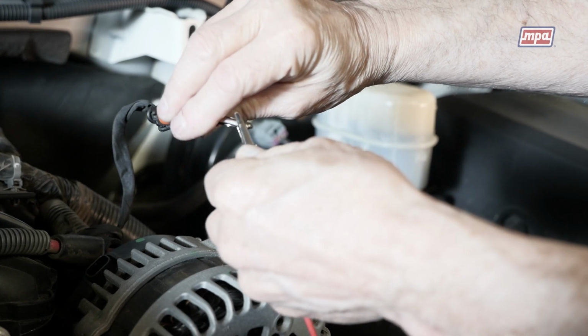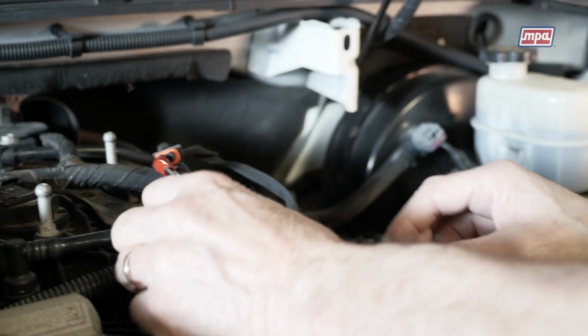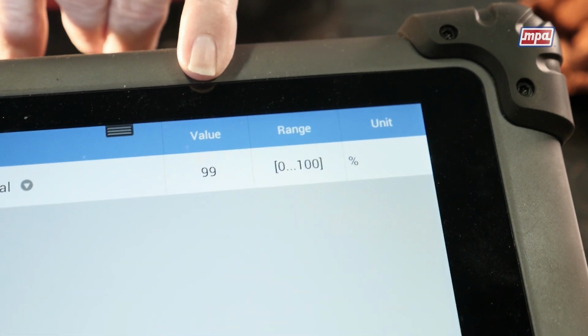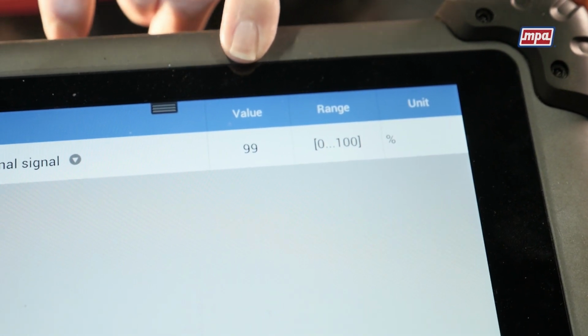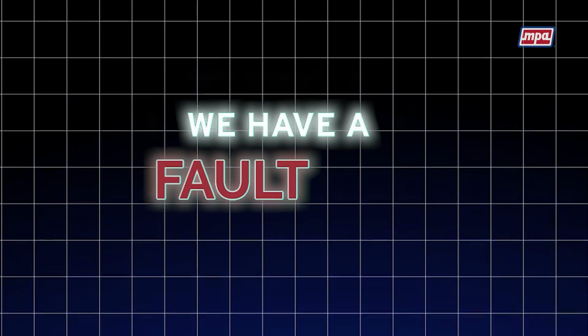At this point, essentially what we're doing is sending a full 12-volt signal through that circuit to the PCM. And the PCM at that point should read somewhere close to 100% duty cycle. As you can see here on the scan tool, we're showing a 99% duty cycle. So again, if we were to connect directly 12 volts to that circuit and it still read 0, then that would tell us right off the bat we either have an open in that circuit somewhere or a fault with the PCM.